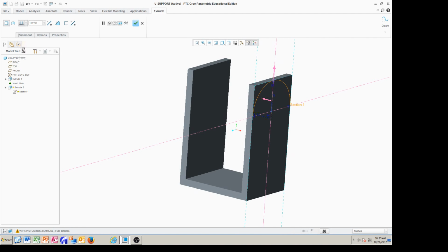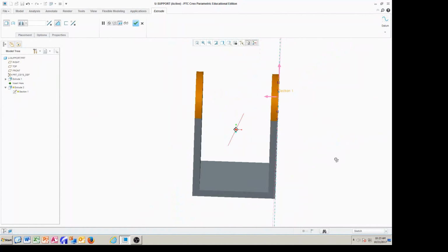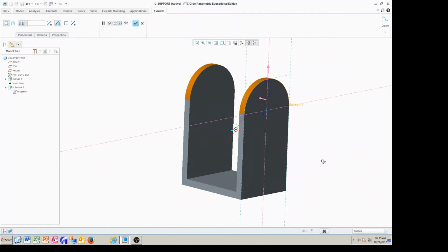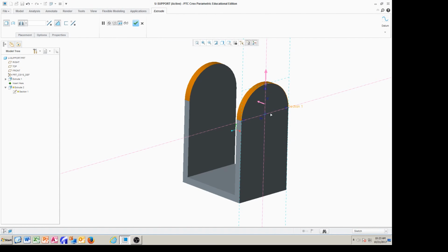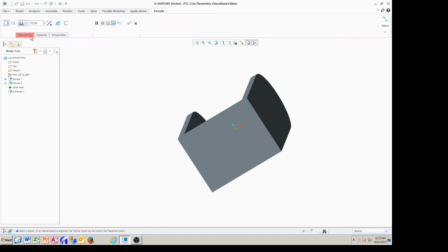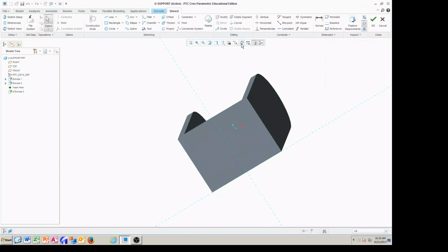Okay, we click on all the way through, and then you remove the materials. As soon as you click on remove materials, see exactly what we're looking for. So we're going to get the semicircular shape and the 140 millimeters from this line. Okay, great. So next, we're going to create a cylinder or the shaft, and that is placed on the bottom